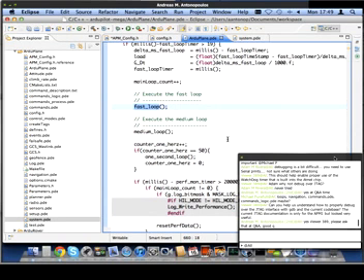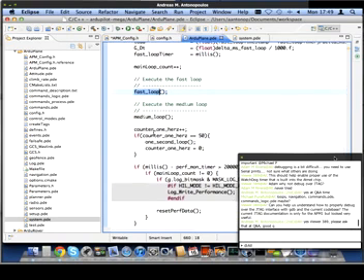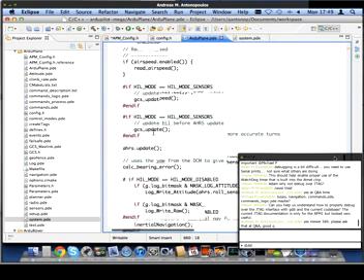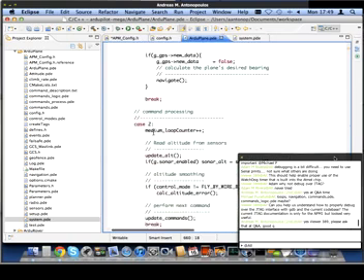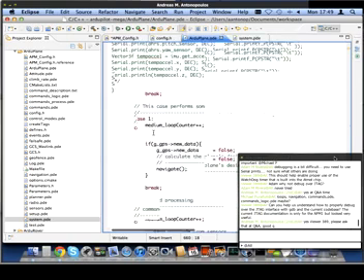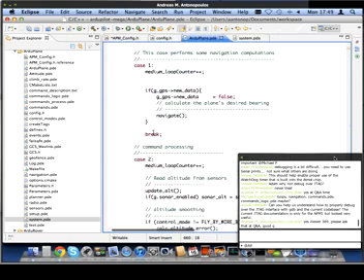And the fast loop on ArduPlane is a 50 hertz loop, so we call the fast loop function, and it does everything that we want to do at 50 hertz, which is primarily the stabilization and the output values to the servo. You can then see that after we call the fast loop, we call medium loop. Now you might think, okay, that means that medium loop is being called at 50 hertz. But the trick that's used inside medium loop is it uses a little switch statement to divide medium loop up into 5 stages.